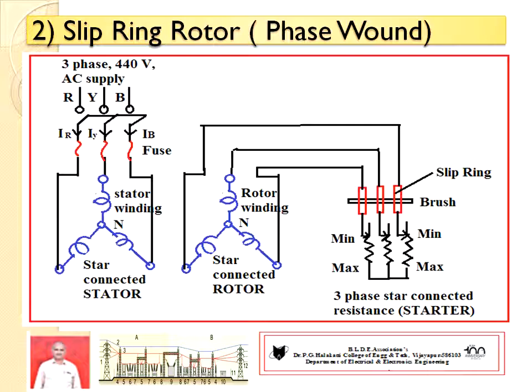These slip rings are kept on the shaft. Now you can observe the resistance position may be kept in minimum position and maximum position. Very important point is that this type of rotor winding has lower values of resistance. Hence, we can't start this type of motor without external resistance value. Otherwise, the motor will be affected by the least resistance value. It may suffer a burning effect also. Hence, we can't start the motor. Hence, we have to keep initially the resistance position in maximum because we are adding this external resistance into the rotor circuit via slip rings.